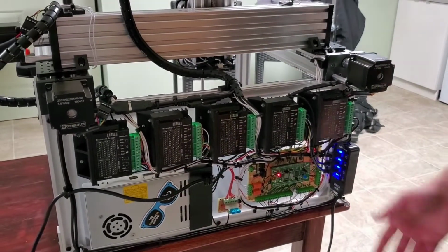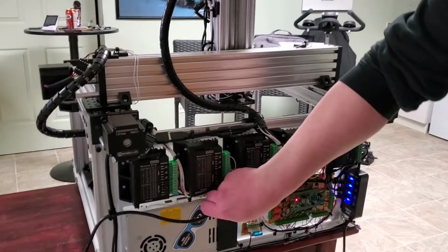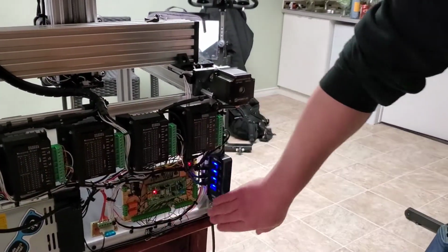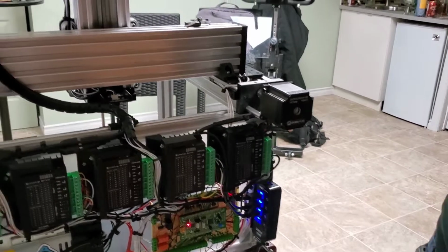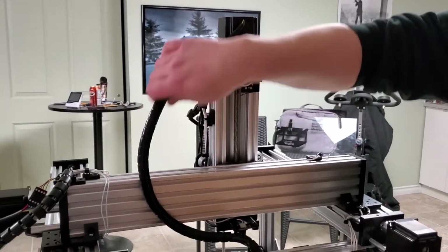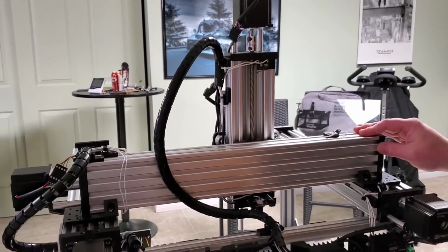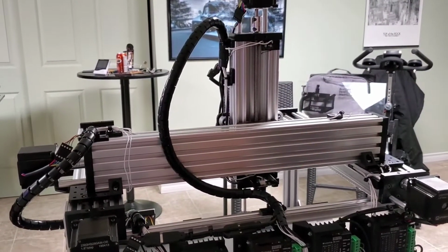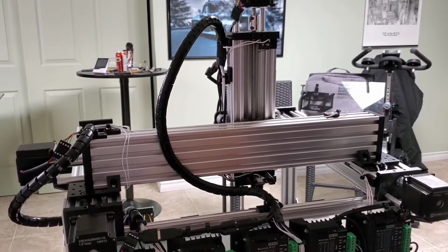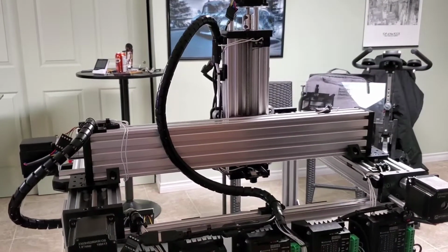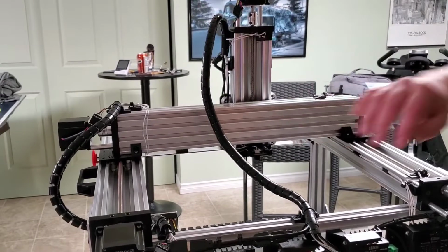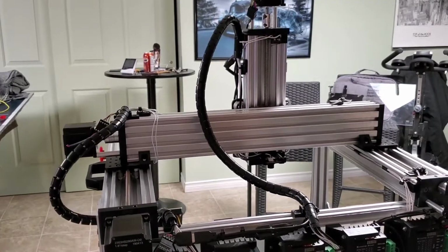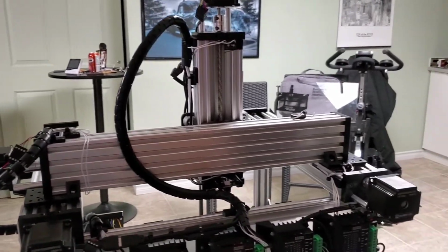It wasn't going to just come and fall apart off the machine. So our power supply has 2 points of strain relief, and there's lots of strain relief throughout the rest of the wire management. We chose to use a spiral plastic loom that works great for moving X and Y positions, which we can illustrate with a simple Y movement. As you can see, the spiral loom works great for managing and encasing the wires for the rest of the motors, the lighting, and limit switches.